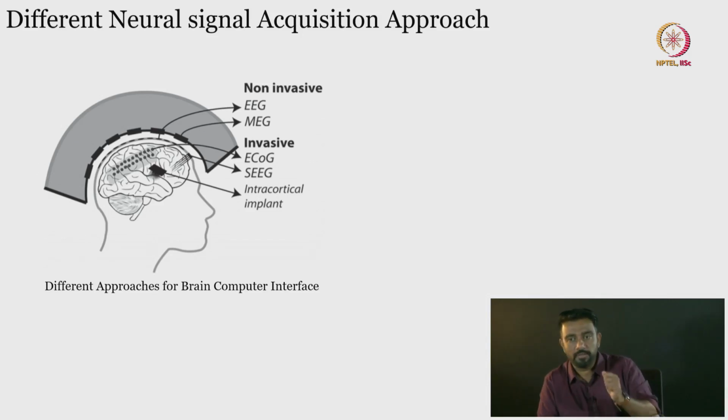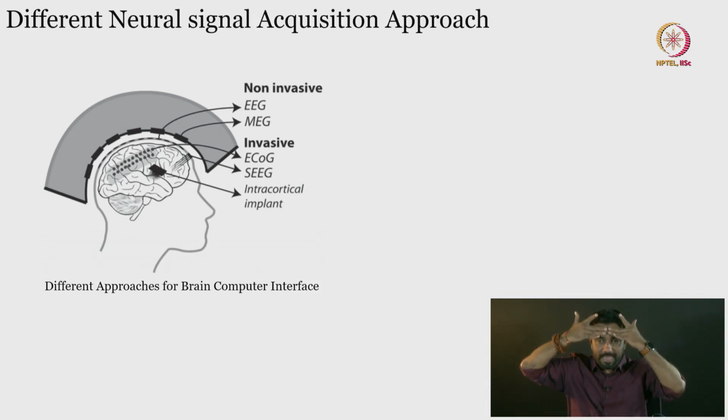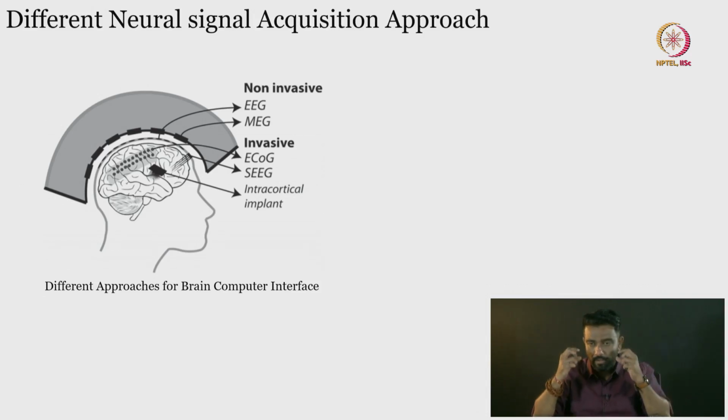But when it comes to the brain in particular, then we look at several things. One is your EEG and second is MEG. Generally you will see the term EEG, which stands for electroencephalogram, but that is outside. That means when we take the signals from the scalp, right, then you get the EEG. The voltage value, the amplitude that you find in the EEG signal, is way lower than the amplitude of ECG or EMG. For ECG and EMG, the voltage range is millivolts. For EEG, the voltage range is microvolts.